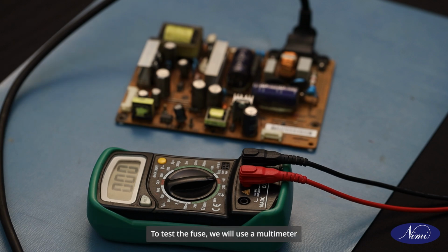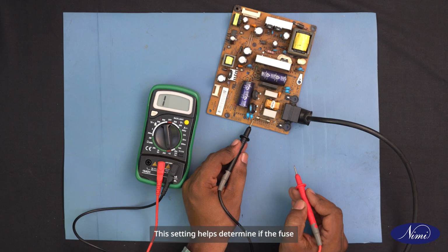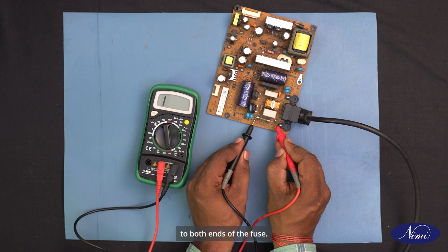To test the fuse, we will use a multimeter set to continuity mode. This setting helps determine if the fuse has a continuous electrical path. Attach the multimeter's probes to both ends of the fuse.